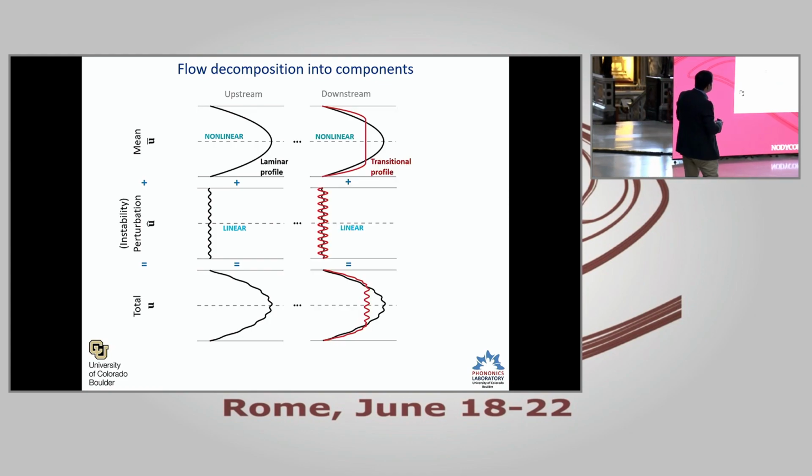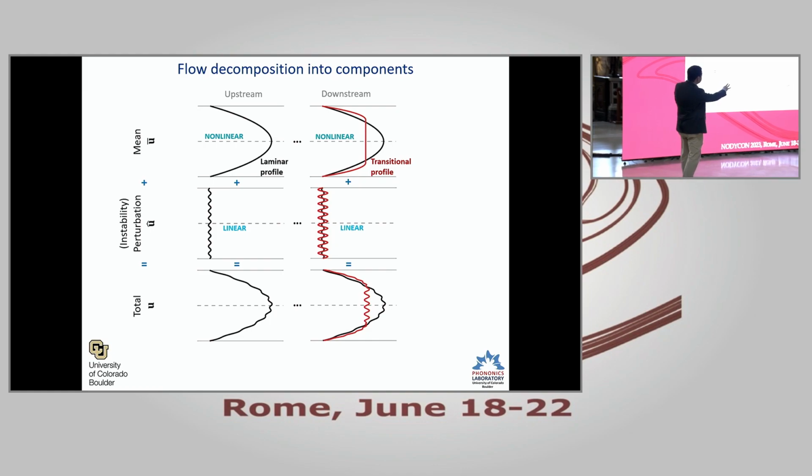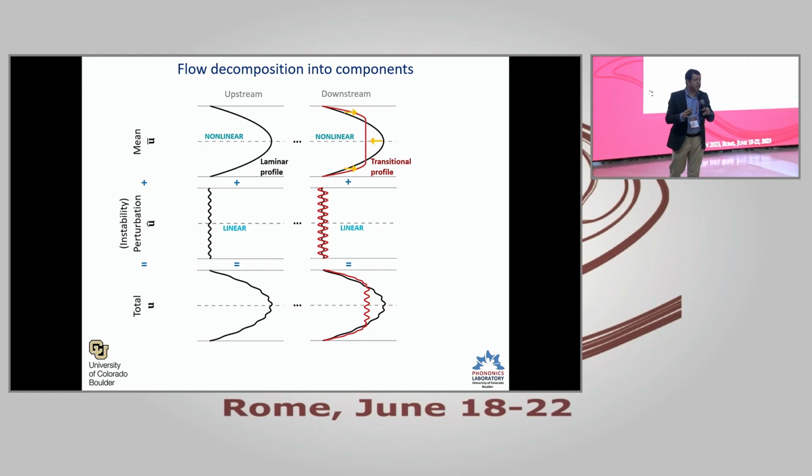Now, what happens is that as the flow progresses, the instability grows. And this is really where you begin to see the very early birth of turbulence, in the sense that momentum transfer takes place outwards. This is an exaggerated view, of course, but you begin to see this qualitative change in the profile, and it's all because of that instability.